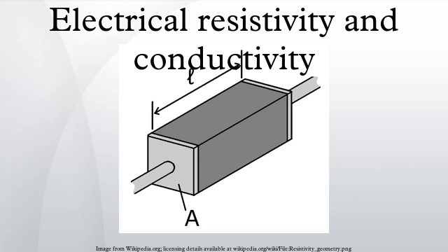The formula can be used to intuitively understand the meaning of a resistivity value. For example, if l = 1 m and A = 1 m², then the resistance of this element in ohms is numerically equal to the resistivity of the material it is made of in ohm meters. Likewise, a 1 ohm cm material would have a resistance of 1 ohm if contacted on opposite faces of a 1 cm cube. Conductivity sigma is defined as the inverse of resistivity. Conductivity has SI units of siemens per meter.